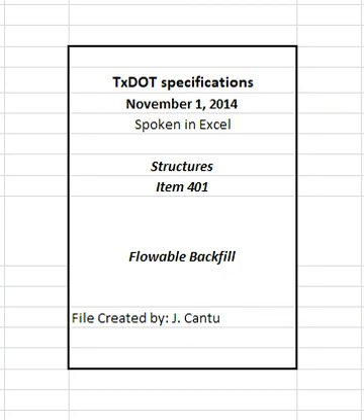Test fine aggregate gradation in accordance with TEX 401A. Plasticity index, PI, must not exceed 6 when tested in accordance with TEX 106E. 2.5 Mixing water. Use mixing water in accordance with Item 421, hydraulic cement concrete.